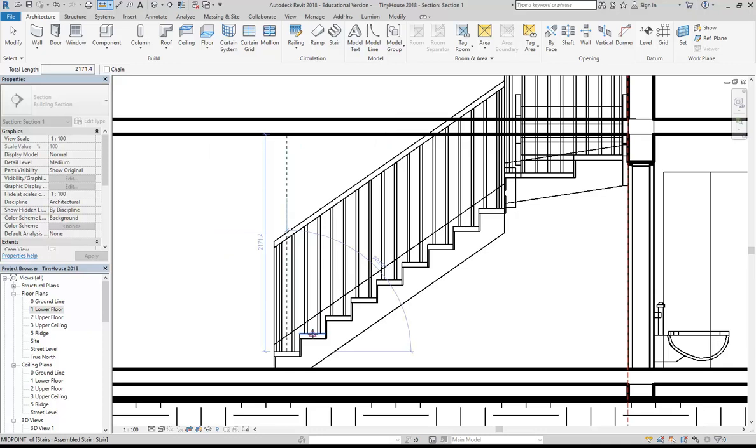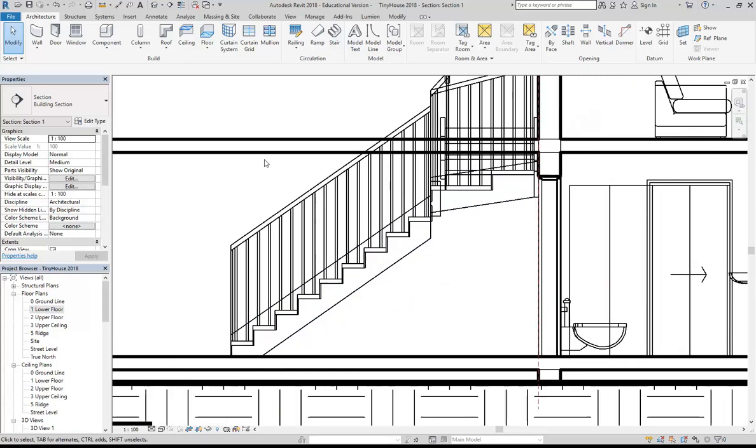So then from the second step, measuring to there, and I'm going to have probably a ceiling under this as well, but for now, even to there, it's 1992. So I'll get headroom if I want to have that first step covered over by what's above, but then from the second step, I'm not. So really, the void for that stair may as well be the shape of the stair. But you'll find if you've got a higher ceiling, that you may be able to get some extra floor space over the top of your stairs.